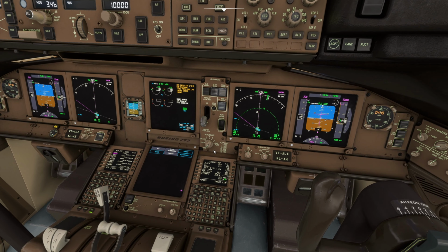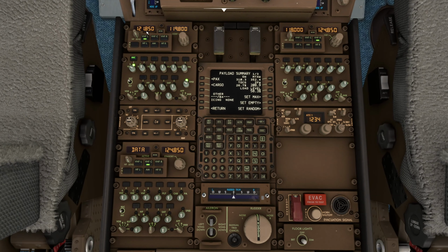Next, autobrake selected to RTO, VHF 121.85 delivery, and I'll put the ground frequency, which is 121.9. I'll put it on active, and the tower frequency will be, I think, 118.1. Is set. VHF center, VHF right, flight. These are the switches that actually keep on. And weather, I'm gonna check on auto. Weather plus turbulence should be selected. VHF center should be on data.